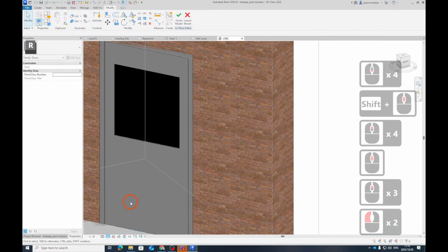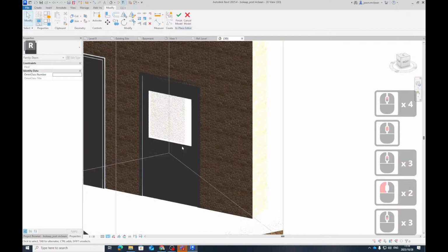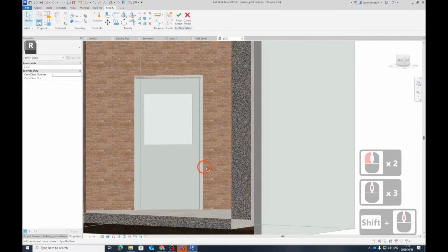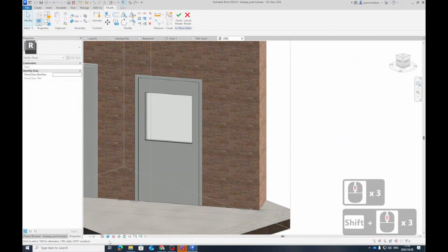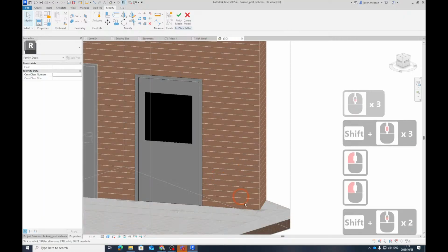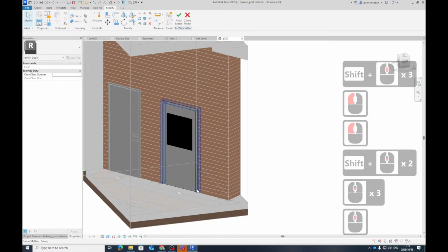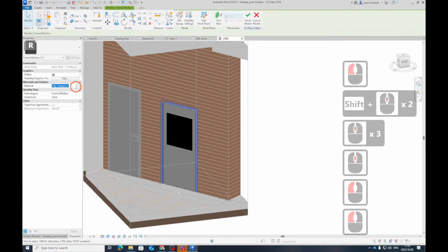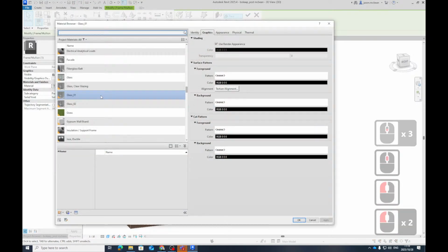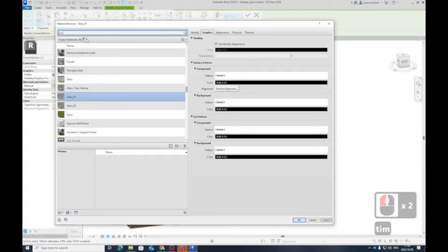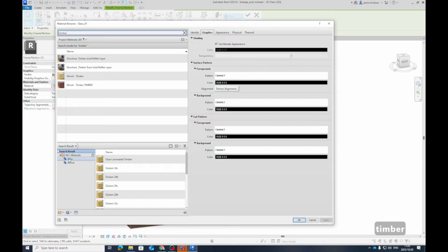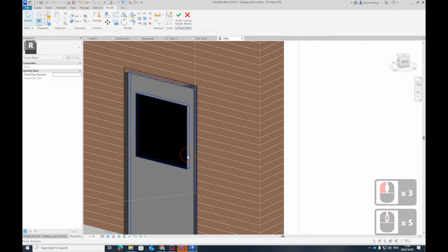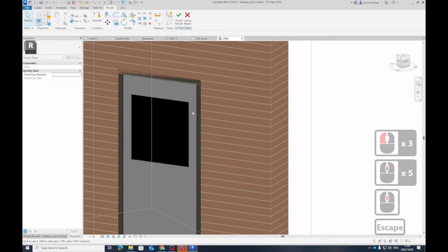Realistic view, ideally you want to see glass as translucent, okay. This will just make your computer quite slow. So you pick your poison, okay? But now, door frame, I can add a timber to that. I can add a material, timber. So if we go timber, just remember at the bottom here, you've always got these materials that you can always add. I'm just going to change it to that one. Oh yeah, and your opening just needs to be slightly bigger, but that's very easy to do, okay?